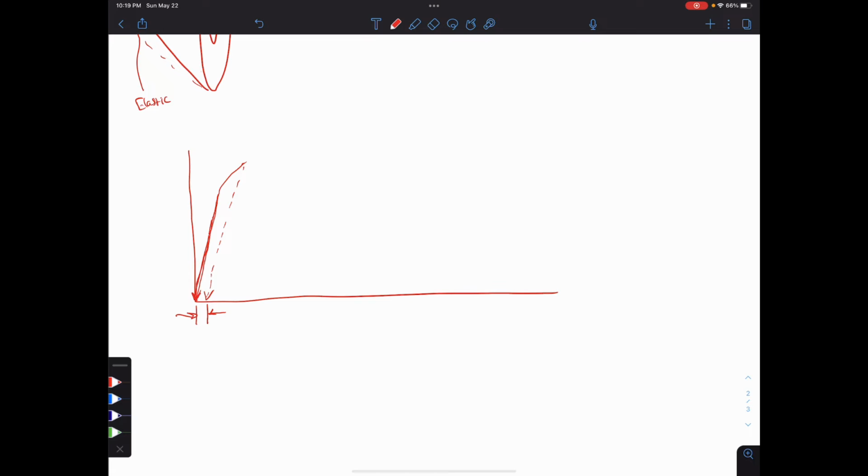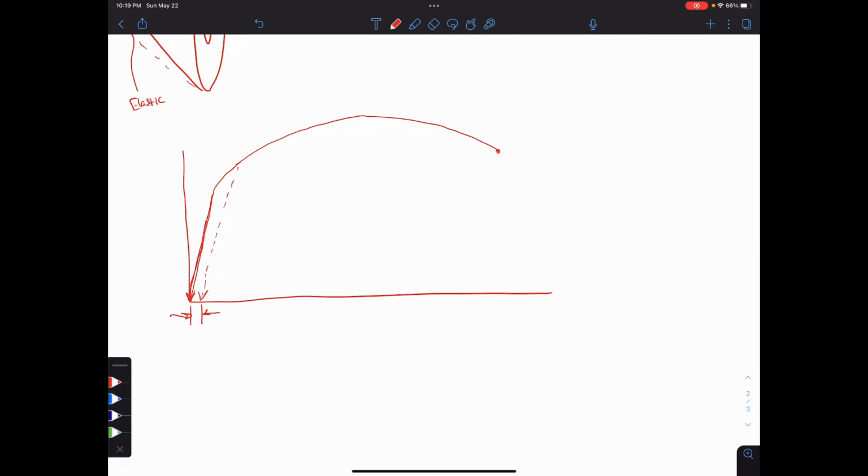All right, we keep pulling it and the load continues to go up. Eventually, we reach a point where I can keep pulling it, but it actually gets easier to move it, okay? And every time I go slow, it wants to turn it into a straight line. Okay, and then eventually it breaks, right? Ultimate strength. Okay, and this is our maximum load here, right? Because remember, this was stress, this side of the graph. So that's as much load as we can put through our material, okay?